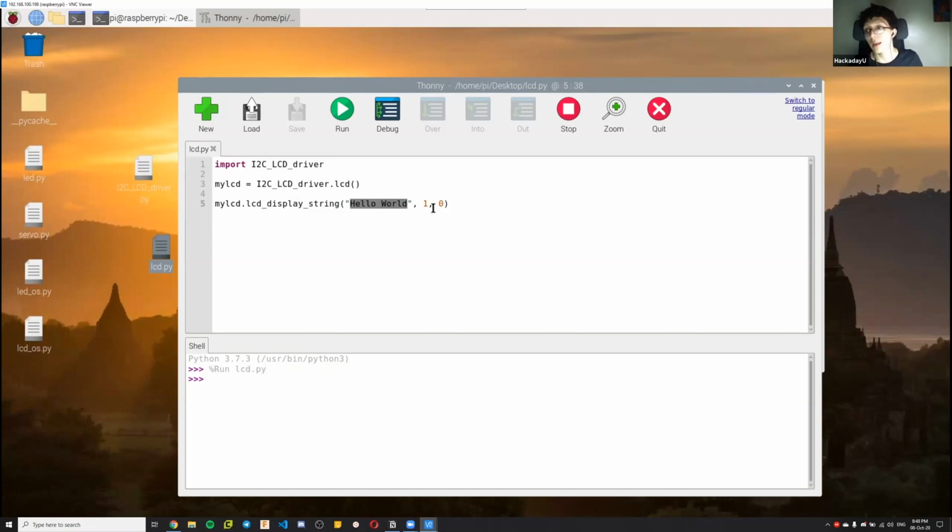If you want to make sure, enable it and reboot the Raspberry Pi through the system. Don't disconnect it and connect it. Then check again the I2C bus that you have, either 0, 1, or 2, etc. It should be 1 if you're using the Raspberry Pi 3.